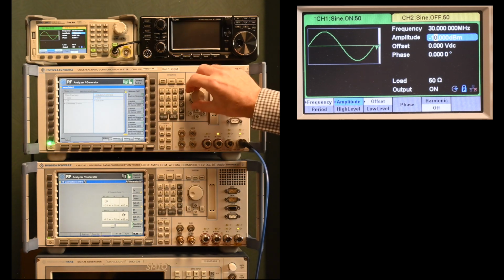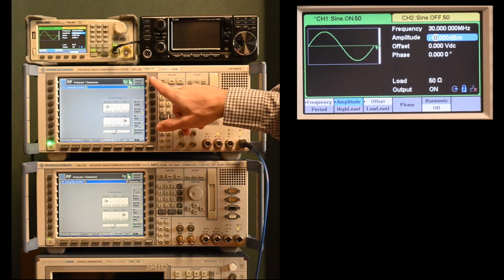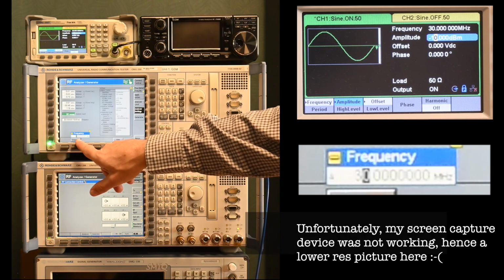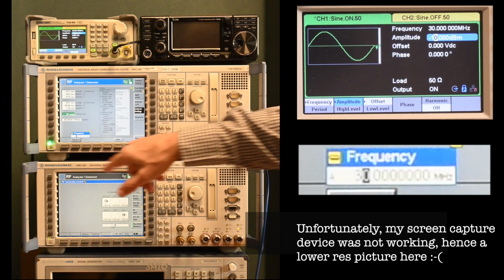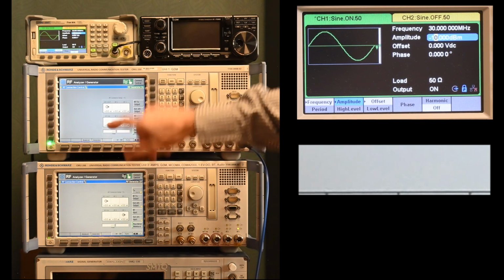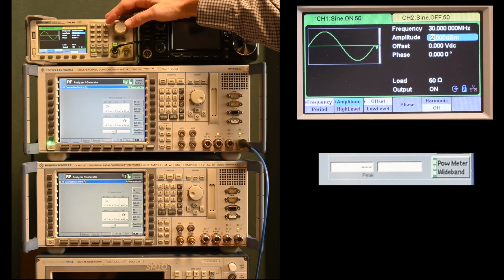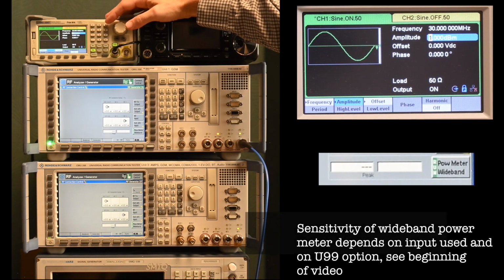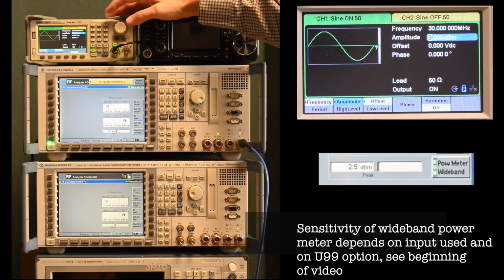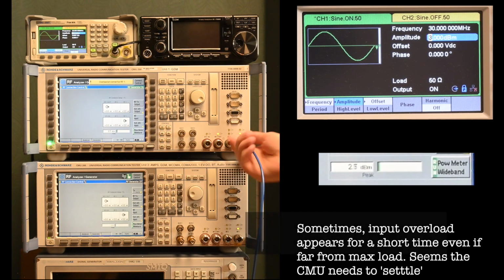So I'm going to the analyzer menu. I've got the right inputs selected. Like I explained before, it's advisable to set the frequency already to the expected frequency range. Now 30 megahertz, that's fine. And we're going to boost our signal. As you can see, there's nothing yet being detected. The wideband power meters are not very sensitive. They will come in right here at 1 dB or so. Sometimes we see a short overload condition. That happens more often at the device. I'm not worrying about that.